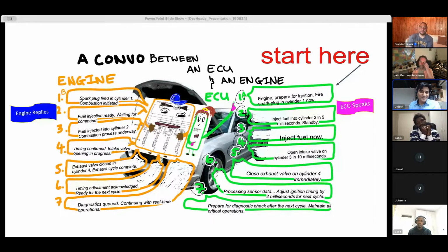Those who write Arduino code know there is a millis function through which you can do a little bit of multitasking. It's not real multitasking, but a kind of multitasking. Then I moved to bare metal where I was handling interrupts. Now, I think in the last engineering hour I spoke, even if you have a lot of interrupts, you will not use them because it gets too complex as a design. Software designs get too complex.